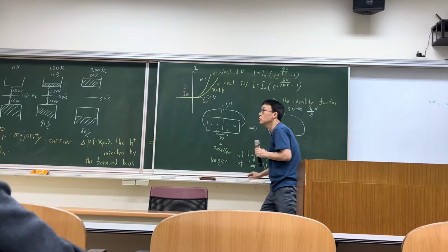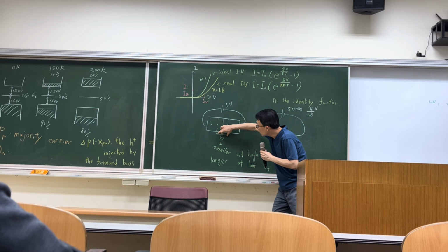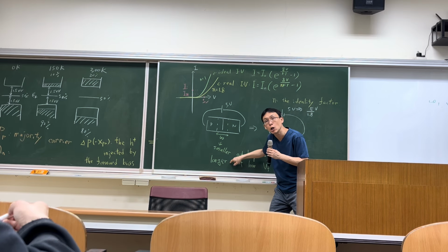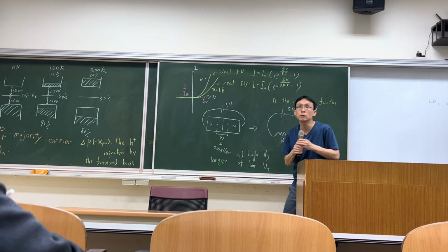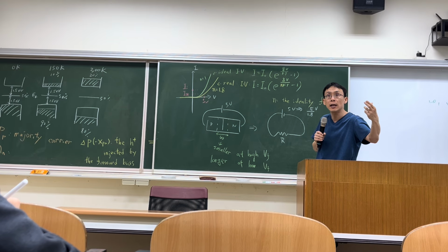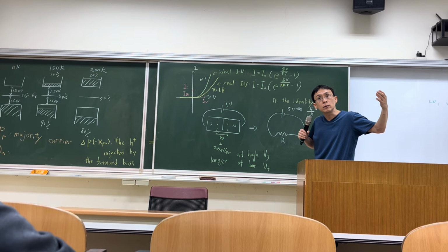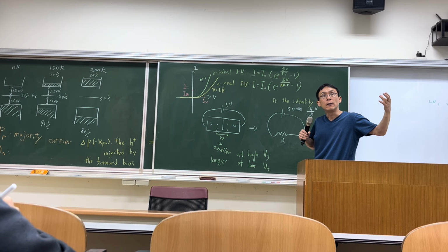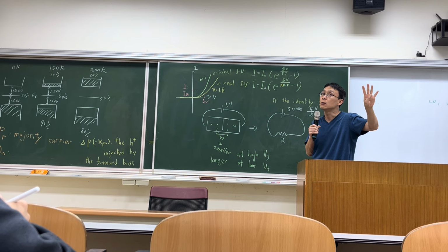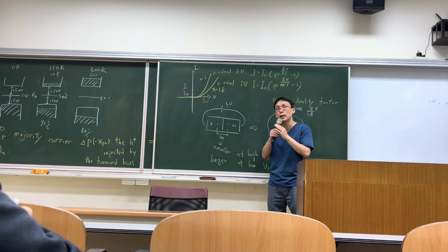So when your bias is small, your depletion region W is longer, which will give you more chance to see electrons and holes recombine in this larger depletion region. So the assumption is not 100% true, especially when you have a low bias, because at low bias, this depletion region is wider.